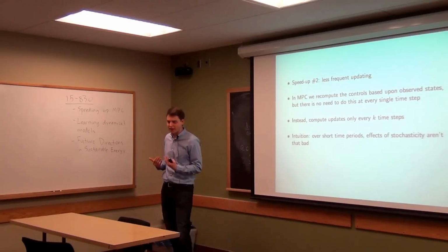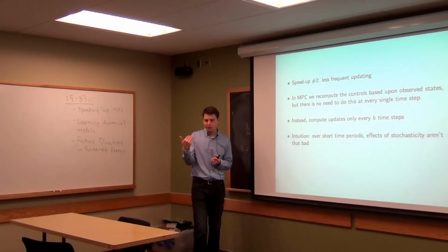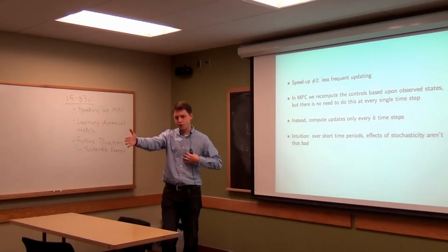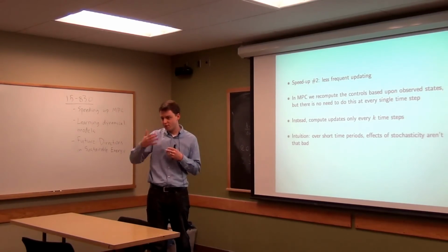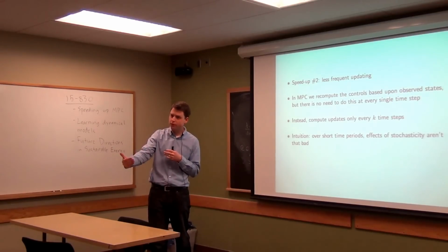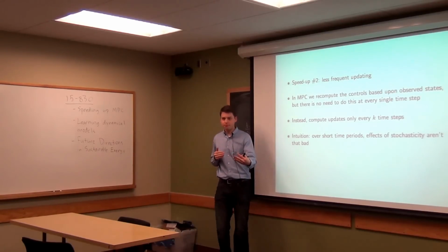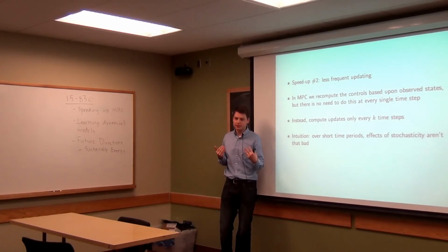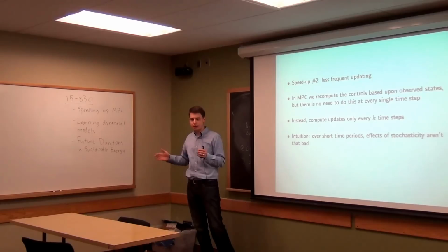In reality, you don't have to think about solving this every single time, right? The reason why we wanted to use MPC, why we didn't want to just solve it once and execute our actions going forward, is that the stochasticity can build up over time, right? So over time, you will have more error in your system. Things will diverge more from what you thought they were, and so you will do badly. But over a short time, this isn't as much of an issue, right? Because over a short time, probably the noise won't be that much, and so you can just execute exactly what was planned for several steps in your control task.